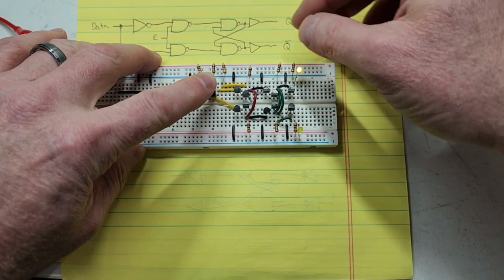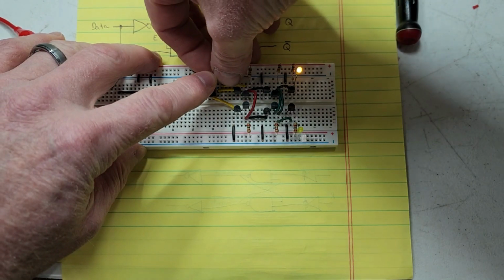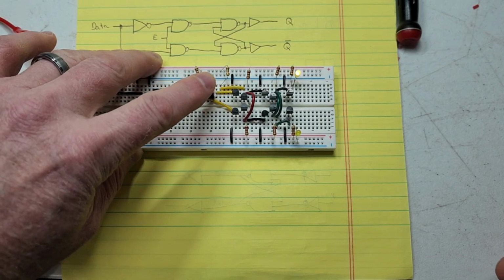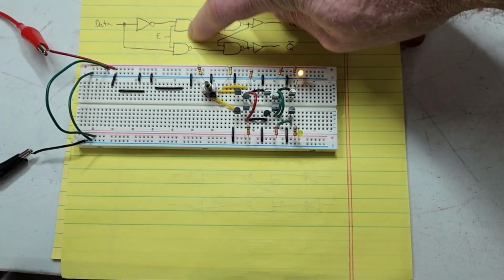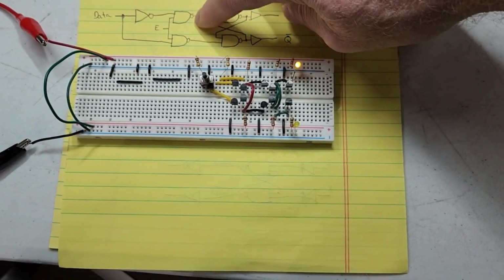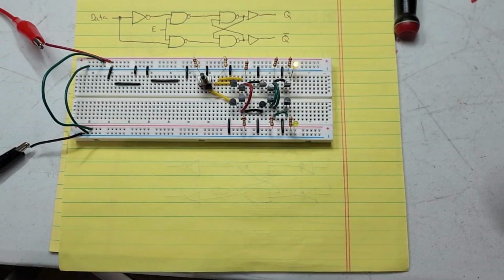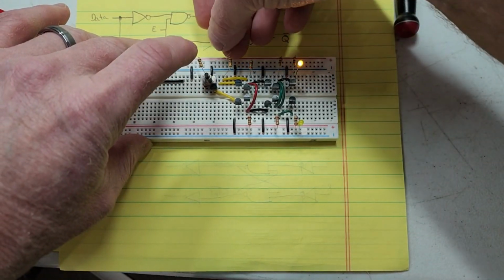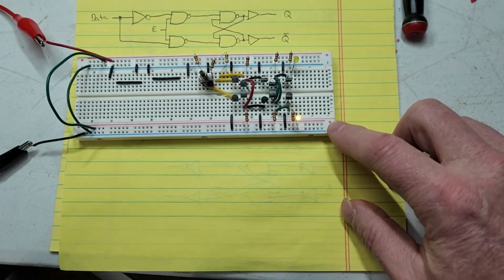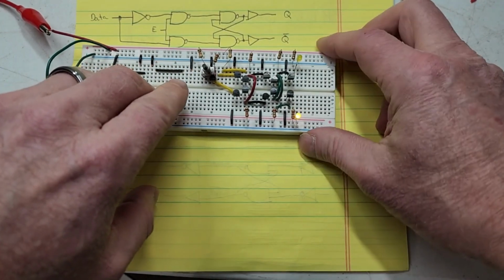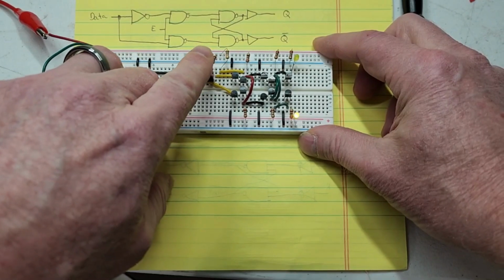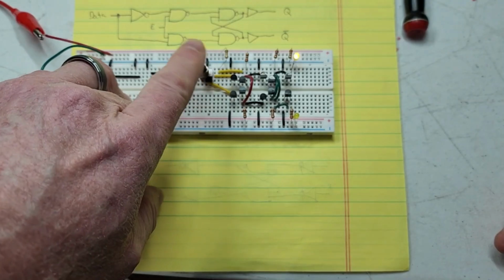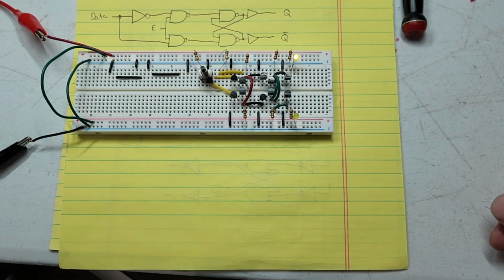put some data in, and then I can remove the enable pin, and when I release it, the data stays there. See, because these 2 gates, these 2 AND gates or NAND gates, are never going to be made because the enable pin is removed. So my data stays. See? And if I put the enable pin back in, it resets. See that? And now I can go back to changing the states. Data going in, put some data in, remove the enable pin, and it stays. Okay? So that's called a data latch.